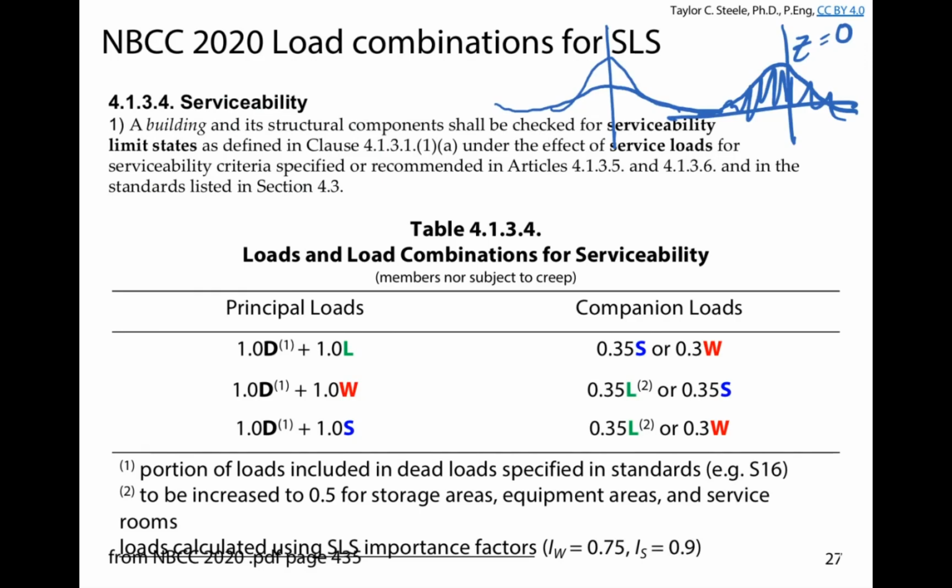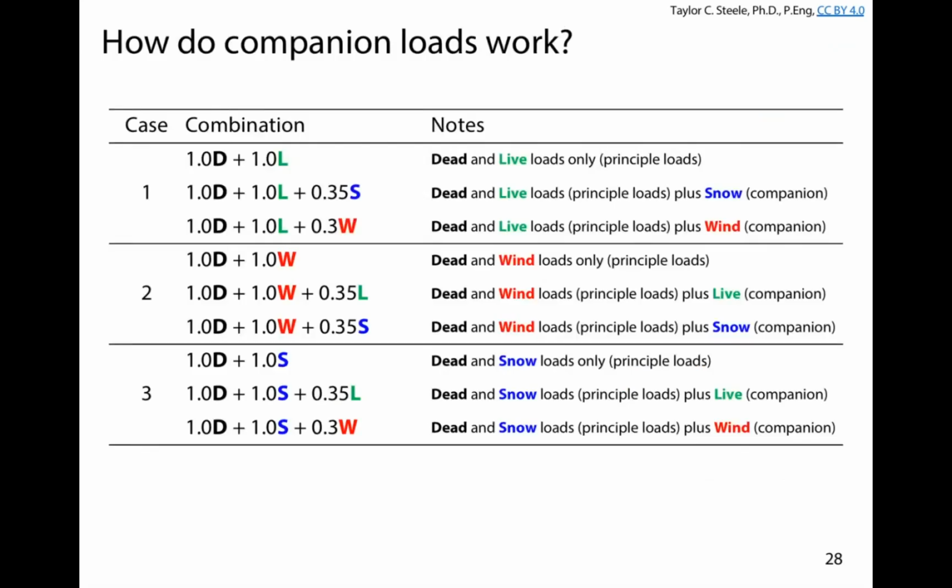Okay, so slightly different load factors. They work in a similar way. We're going to be looking primarily at mostly live and snow load type deflections. We might also be looking at wind load deflections. For example, we want to make sure the building doesn't get pushed too far to the side from the wind so that the pretty stuff on the outside doesn't start to crack and fall off.